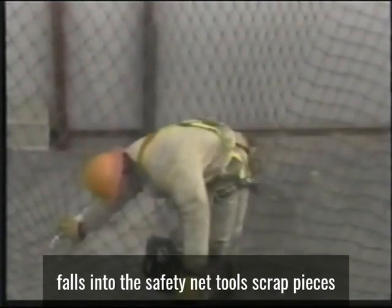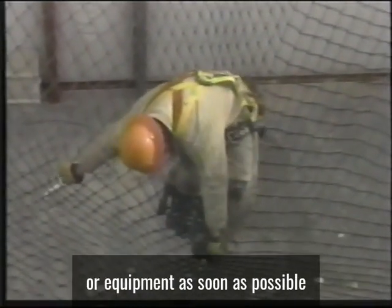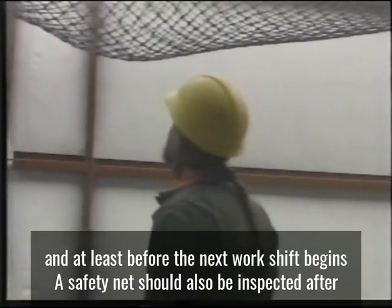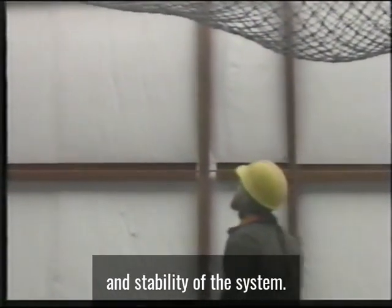Remove anything that falls into the safety net, tools, scrap pieces, or equipment, as soon as possible, and at least before the next work shift begins. A safety net should also be inspected after anything is dropped into it that might affect the strength and stability of the system.